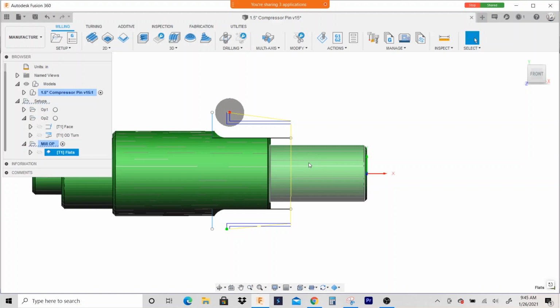So I don't know how well y'all can see this, but say that you've got to cut this part. If I cut here and then come over here and do the same thing, on one side this is conventional milling, and on this side it's climb milling. That's because climb milling or conventional milling is based off the direction of feed, which is based off the feature.